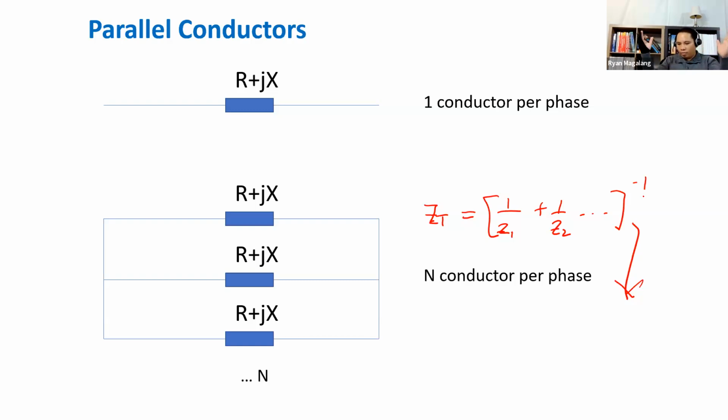So as you have more and more generators connected to the grid, which is essentially like this thing happening here, paralleling more and more impedances, because we express the utility as an impedance when we do short circuit analysis, it brings down the value of the impedance of the utility. Same thing with what's happening with the conductor. You think about it.